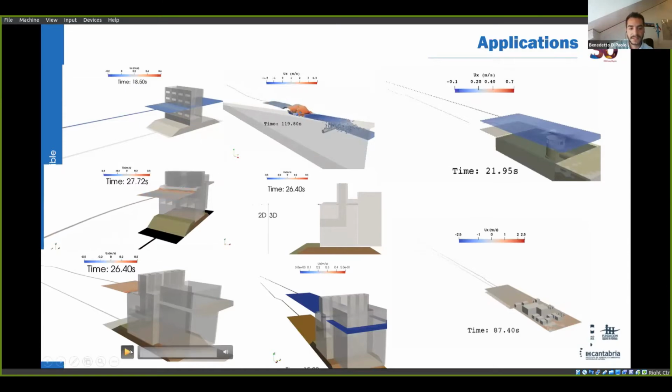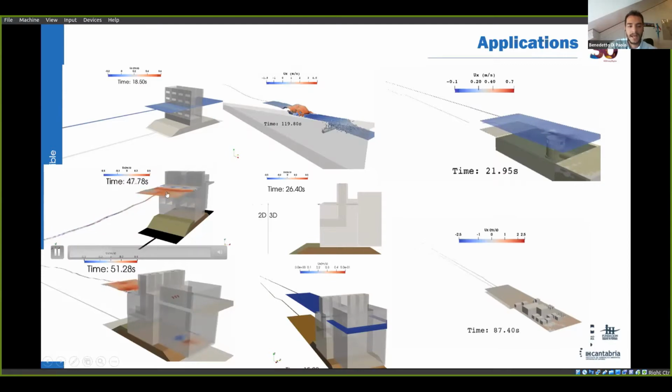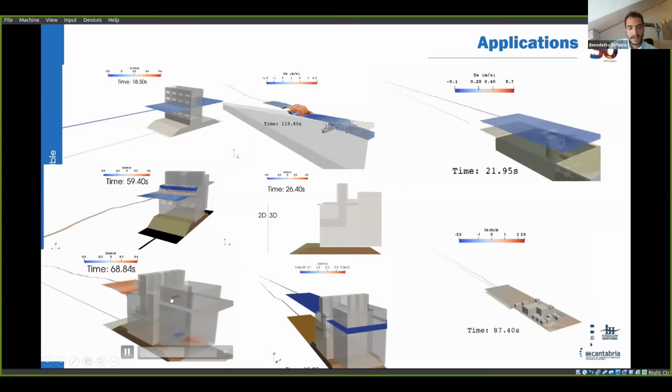And the previous case I showed you in the validation cases is this one. For instance, as you can see here, waves are interacting with the dual wave energy converters, and you can see the oscillation inside the oscillating water column and the overtopping device, which are impacting the structures, also entering some pipes, and then the overtopping discharge is filling this tank outside the breakwater.